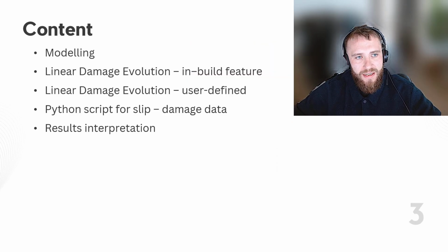Today's content, I want to focus on modeling linear damage evolution as an inbuilt feature in ABAQUS. Also, I would like to introduce how you can define user-defined evolution, and we will compare the inbuilt and user-defined damage parameters.